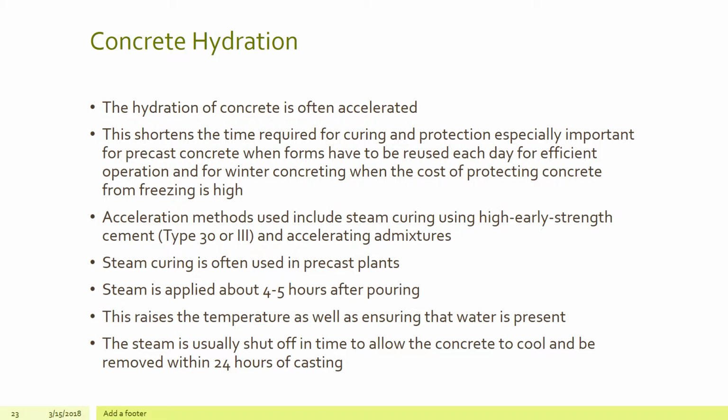Concrete hydration. The hydration of concrete is often accelerated. This shortens the time required for curing and protection, especially important for precast concrete when forms have to be reused each day for efficient operation, and for winter concreting when the cost of protecting concrete from freezing is high. Acceleration methods used include steam curing, using high early strength cement, and accelerating agents.